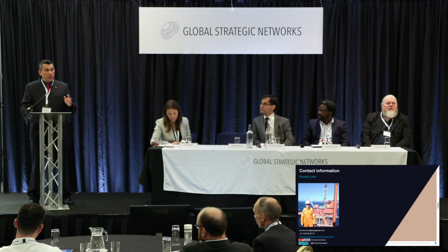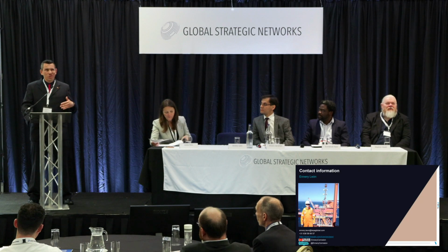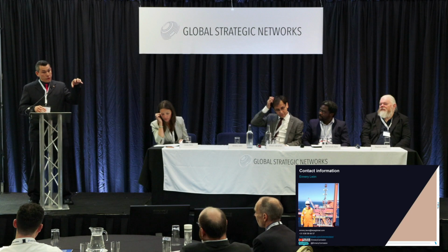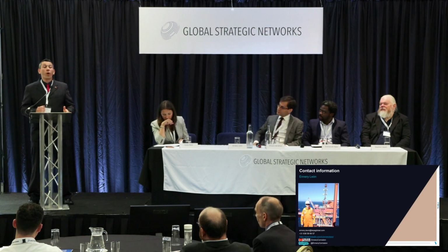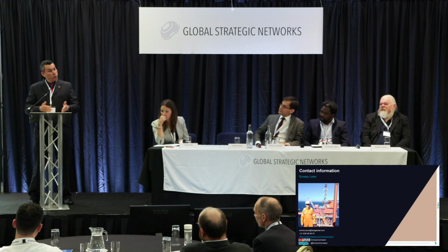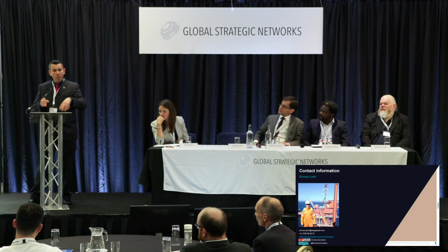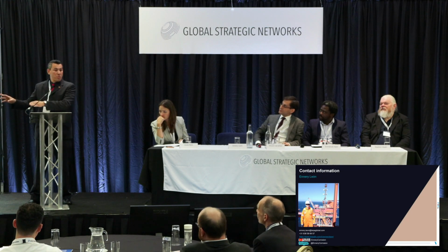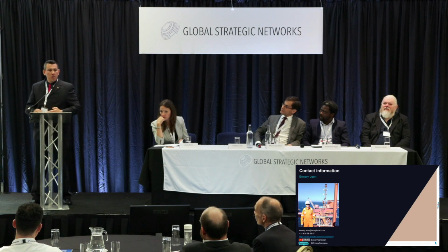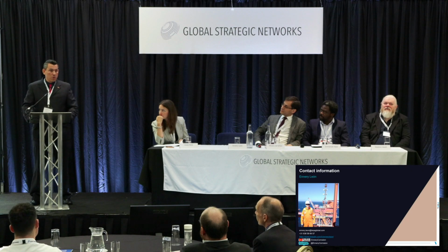And also, it's not advised, especially in our business, but these probes are quite durable, so to say, and you can even use them for a couple of days. Let's say well number one, you do your optimization. After a couple of days or weeks, if you have the tools to do this online, you can retrieve it, close this one, go to well number two, and use the same probe. If that probe matches the expected corrosion rate that I explained, you can move them. So they are quite flexible.